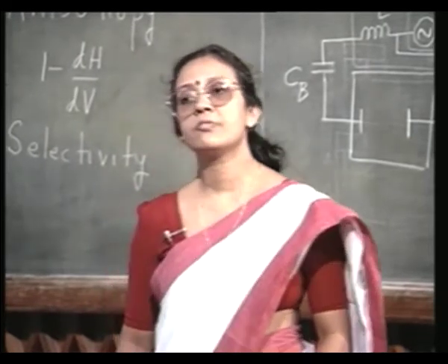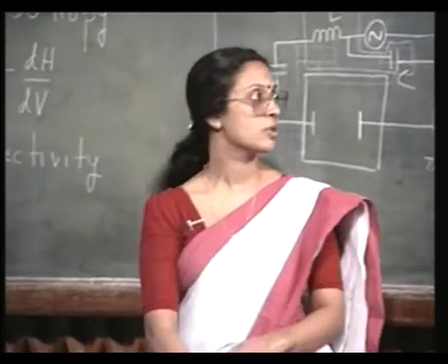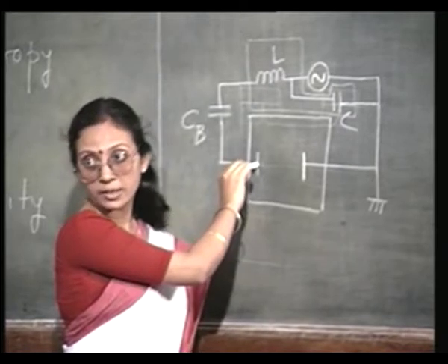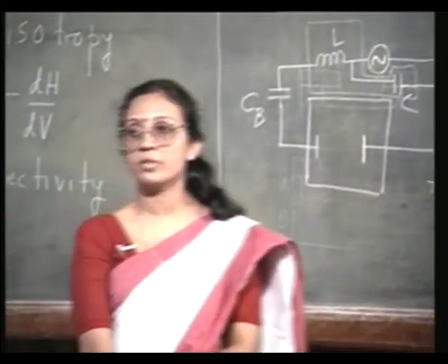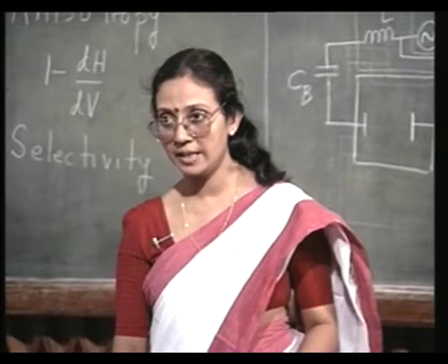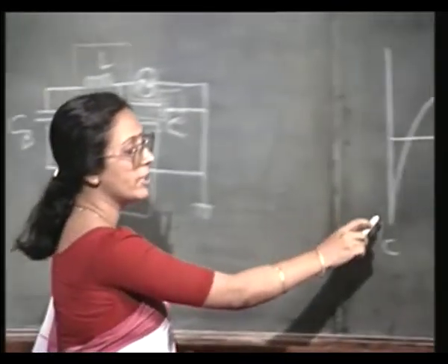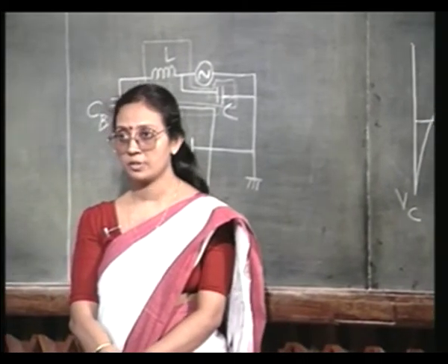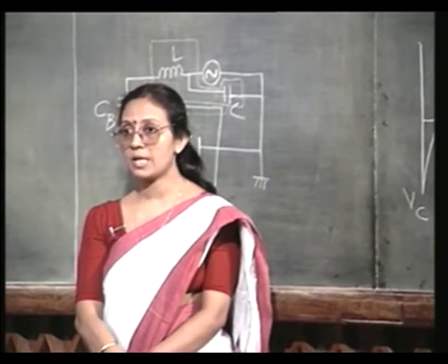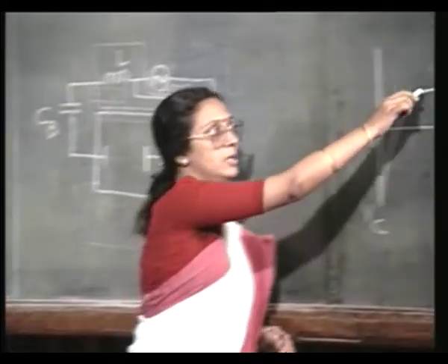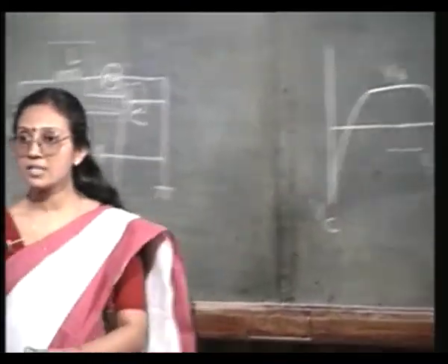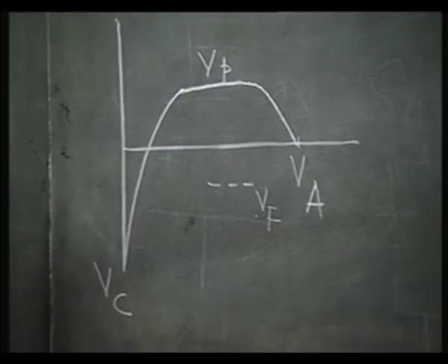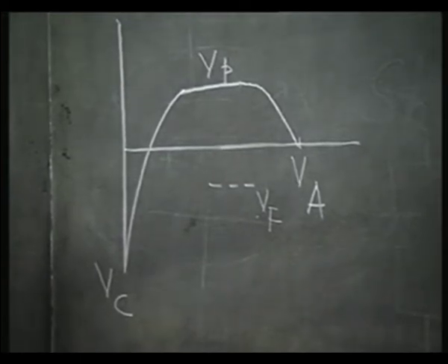However, if you place your substrates on this other electrode, the RF powered electrode, which is commonly referred to as the cathode, then since there is a very high negative sheath potential developed between that electrode and the central portion of the plasma, you have a large potential difference and therefore the ion bombardment energy will be very high.